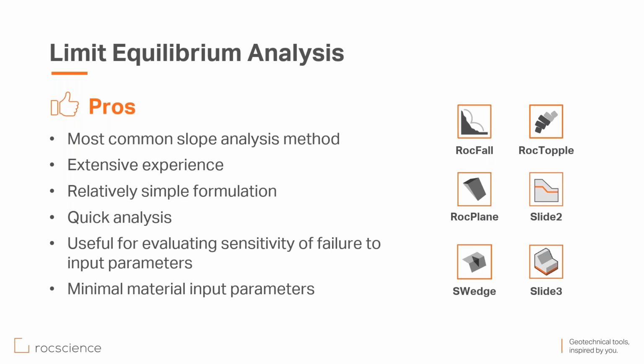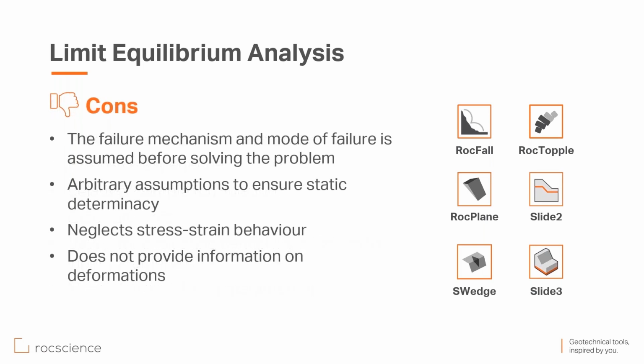And the setback from that, you will see in the cons here later, is that since you are not providing the stiffness of the material or are neglecting the stress-strain behavior of the material, limit equilibrium cannot provide you information on deformation.